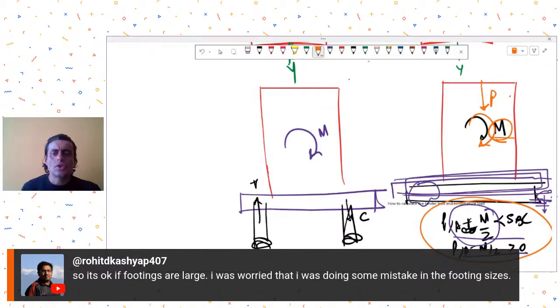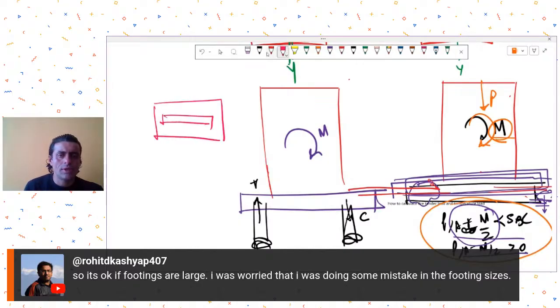Yeah. So you can do one thing: tie these footings with some adjacent footing. I mean, this shear wall footing, you can always try to tie it up using strap beams or tie beams at footing level to the other footings. That is always a good option to distribute the overturning moments. For example, this is your shear wall and footing, and then there is some adjacent column.